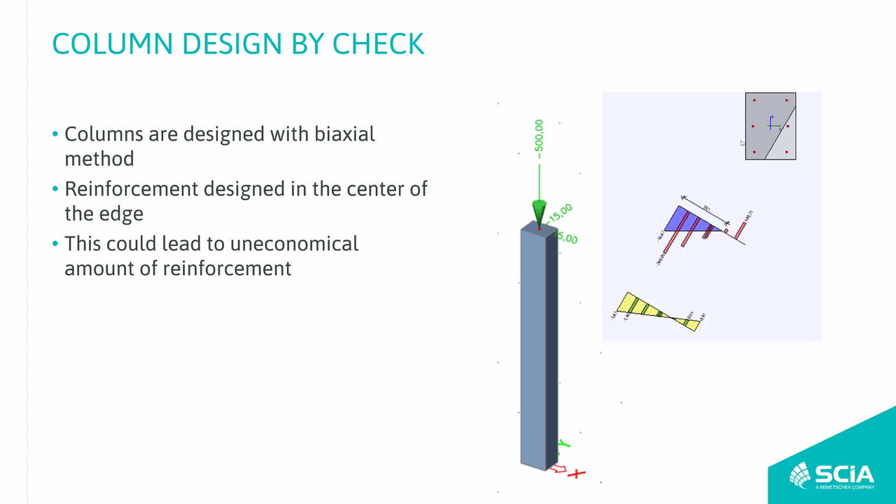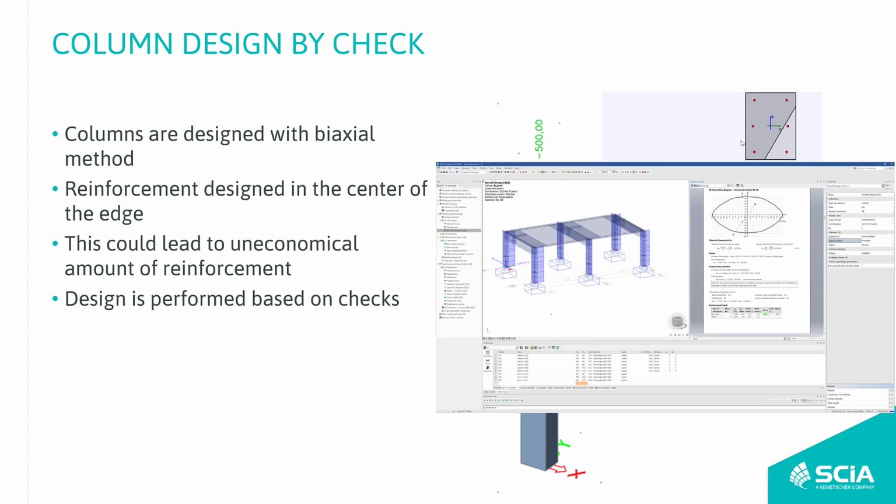prerequisite for the calculation. And if you have the designed reinforcement, you will put it to the cross-section, then run a check, you will see that the utilization of a cross-section is so low just because of the used algorithm. We decided that if we have checks where we are checking the amount of the reinforcement, we can use it also to design such a reinforcement.